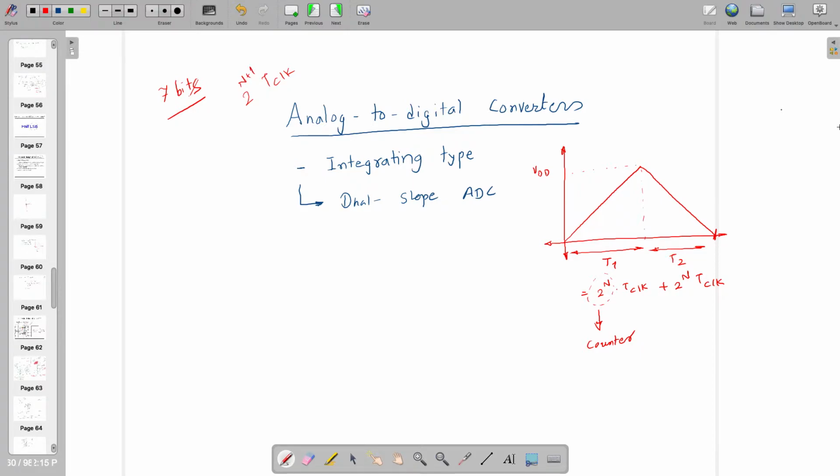So this is going to take more time, even if your clock is as high as 1 GSPS, right? So this whole thing will be divided by 512 times to find out the effective conversion time. There are two things, if I forgot to tell you.